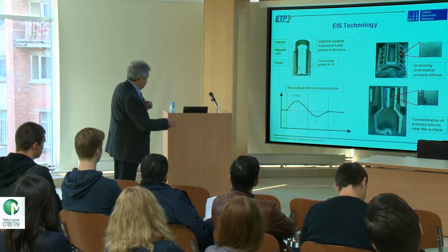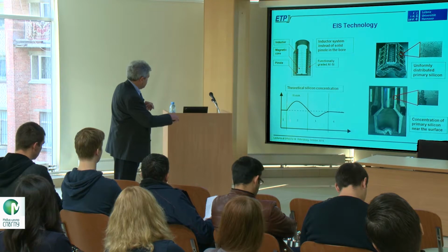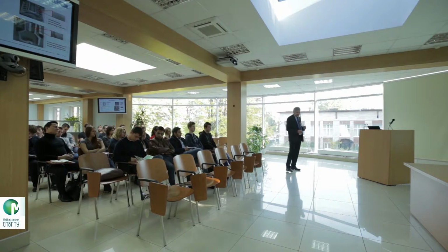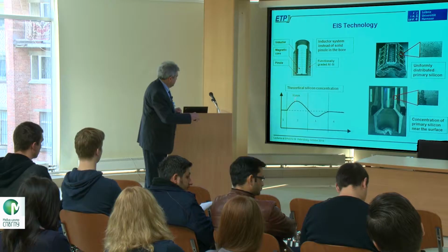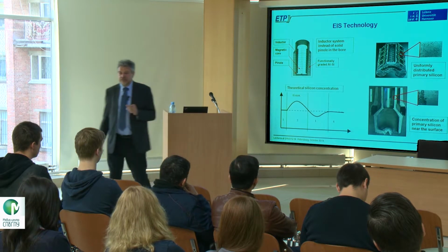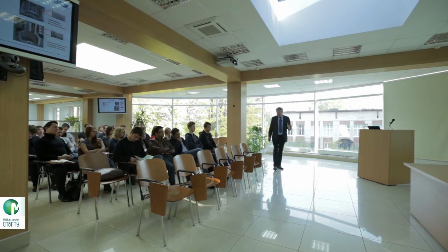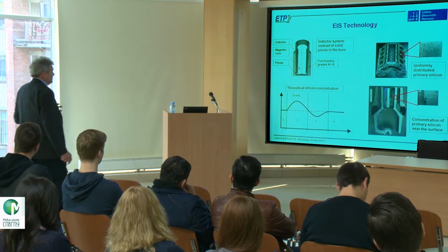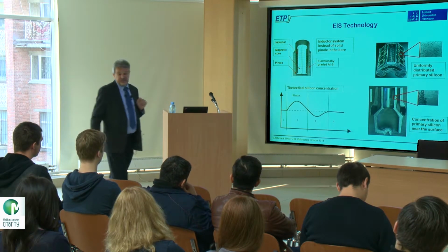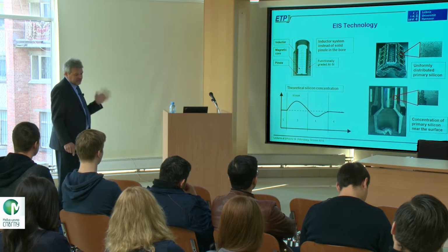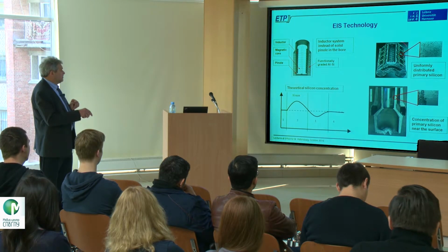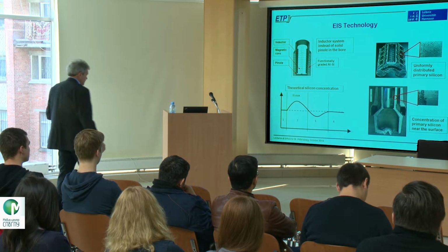And the theory said, okay, after casting you have to treat it mechanically. You take away this surface part here. You have to mechanically make the diameter exact. So then, after treatment, you are with your final surface just here, and there you have a high concentration of silicon. And the aim was, of course, to show that it works. Therefore, our task in this project was to realize such an inductor system. And then, together with some casting institutes in Aachen, to realize experiments, and then finally really to cast such an engine block. And all was done.